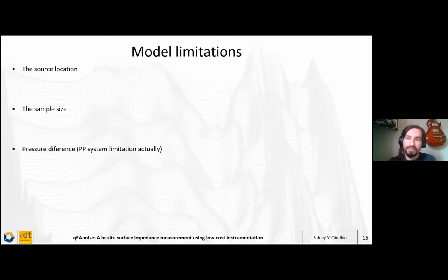For lower frequency measurements, it's difficult to achieve, because you have very long wavelengths and very small spacing. So when, for instance, a 17 meter wavelength passes two microphones spaced 1 centimeter apart, what is going to be measured is basically the same pressure. That will carry a lot of uncertainty for the lower frequencies. That is why it's so difficult to measure the lower frequencies.